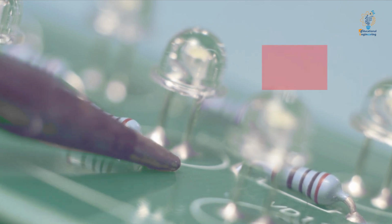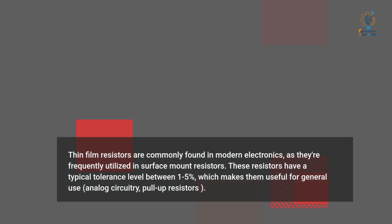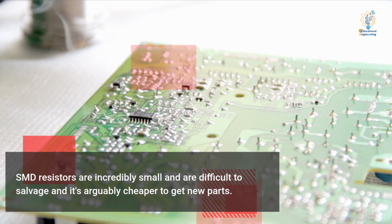3. Thin film resistors. Thin film resistors are commonly found in modern electronics, as they're frequently used in surface mount resistors. These resistors have a typical tolerance level between 1 to 5%, which makes them useful for general use, analog circuitry, pull-up resistors. SMD resistors are incredibly small and are difficult to salvage, and it's arguably cheaper to get new parts.